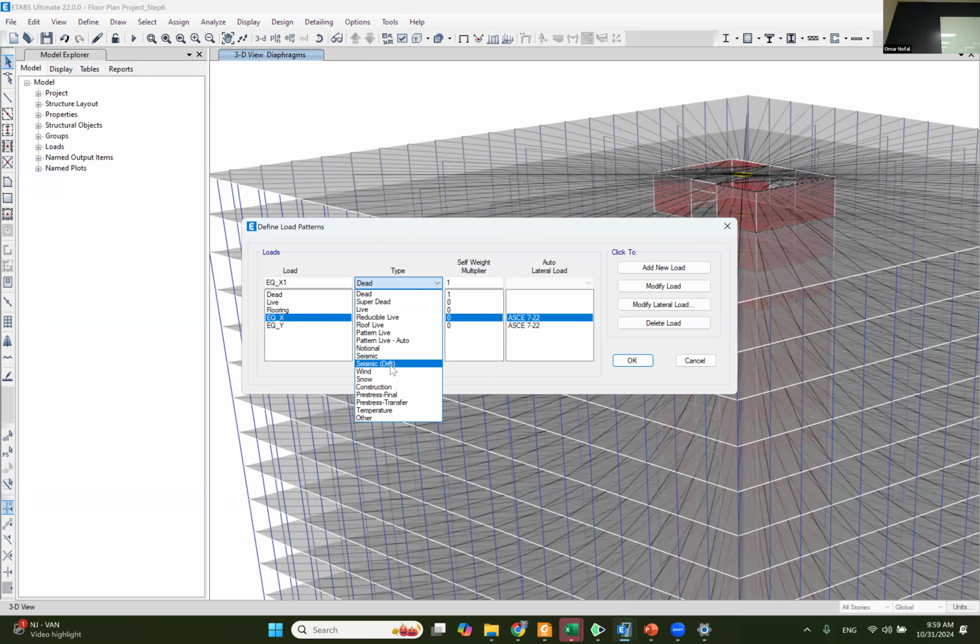Why do we have two separate models? Because when we design for forces, we design ultimate and we reduce the forces with a reduction factor, because of this thing that I told you about, inelastic and elastic. In seismic, we reduce the forces and also reduce the inertia, both of them, inertia and forces.